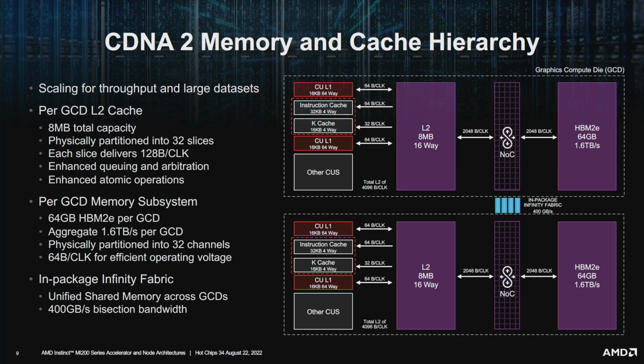These 32 slices are interconnected to the 110 compute units, delivering the bandwidth needed to feed the math. The L2 arbitration architecture was optimized to increase efficiency across varying compute unit load. We also added 64-bit floating point atomic operations to each L2 slice. This allows many parallel threads to reduce data into output values without the need for separate reduction kernels or complex parallel reduction algorithms, and provides high performance even with moderate contention.